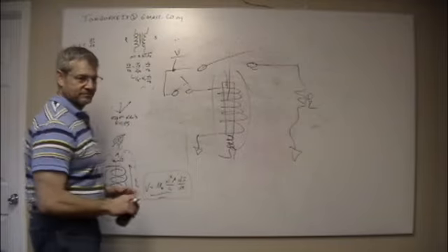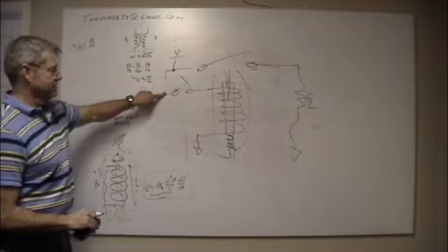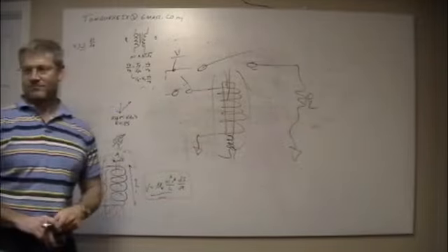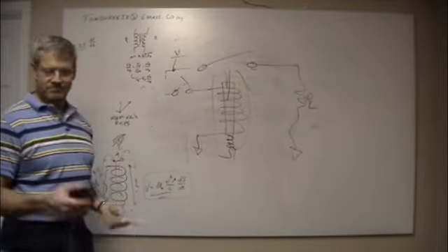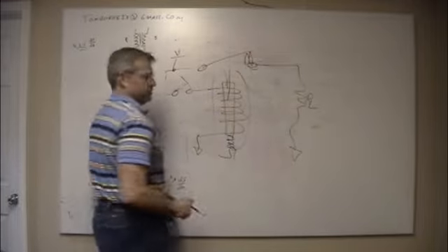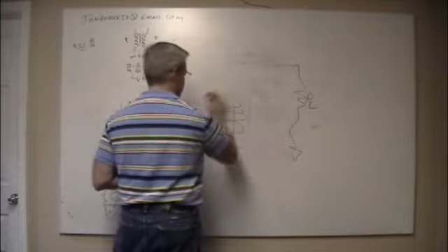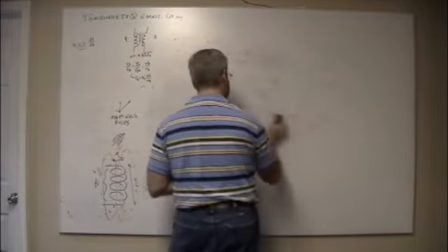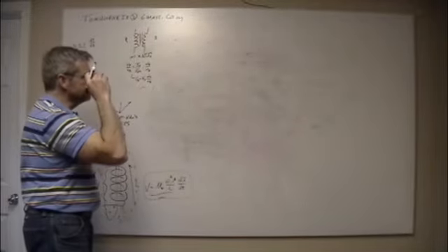For DC versus AC, sure, this could be separated. Yep. This could be a 5-volt battery, and this could be 110 volts AC. And it's all isolated then. There's no connection between the two. Yeah. These have a tendency to arc right here and eventually wear out, but I have replaced a lot of them. But they're good. They are still used, and there's reasons why you would use those over other things, depending on what you're doing.